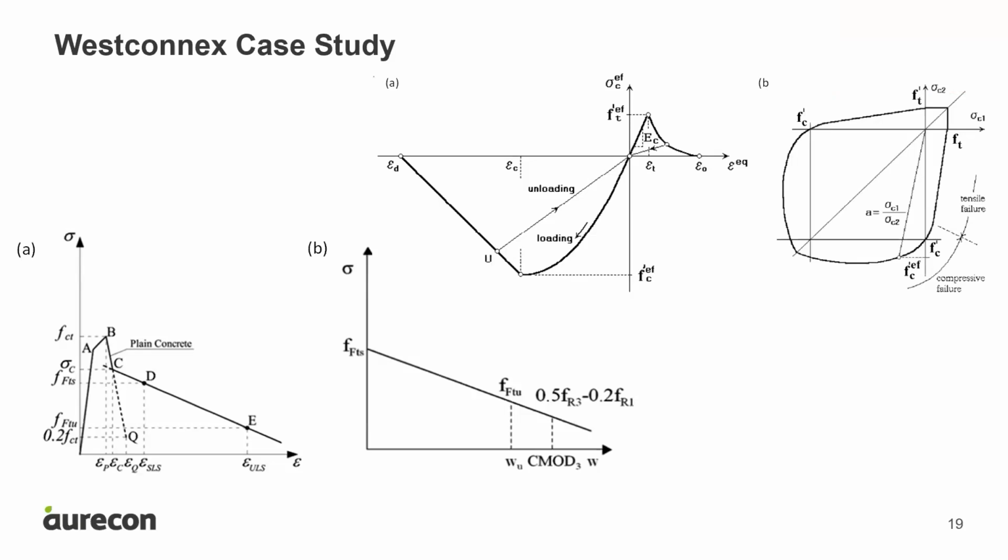So the software is doing this calibration by itself? No, look, my approach, obviously people have different approaches, is that I generate the mesh and see what's a reasonable mesh size. Then when I'm specifying these strains, I'm calibrating against a certain crack width that comes from the beam testing. Then I do the correction of the model at that point. Once I know the mesh size that I want to use, I do the correction of how I input these constitutive relationships. It's almost like a piecewise discretization of the curve intention, and it's linked to the model size. So I know the model size first, then I run, say, a beam test to calibrate, and I see if I'm calibrating the beam test correctly based on that.